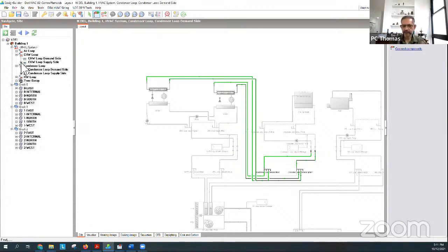So let's do that. Let's put one chiller as the low load chiller, give it 40% capacity, but the other one is a main chiller, give it 60% capacity. And then we will need to guesstimate what is the total size of the chiller that we need. Now one way to do that is, and I did this before the class, so I know what the numbers are.